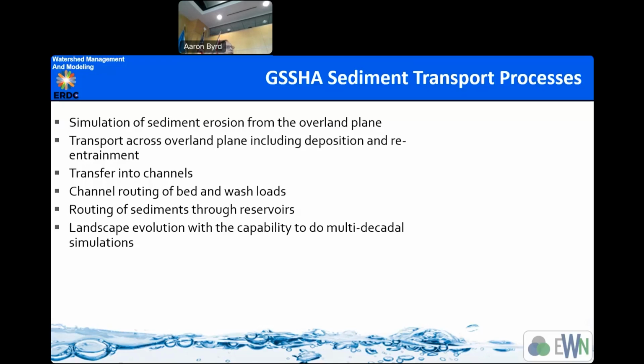And there is another function, so-called transport capacity. So if you have a mass of sediment at a certain grid cell, we have the calculation of transport capacity. And for this transport capacity, basically USLE, all those equations are empirical, and along with so many equations that we use in GSSHA and tested in GSSHA are for the transport capacity. So we'll come to those transport capacity equations as we go along this slide.